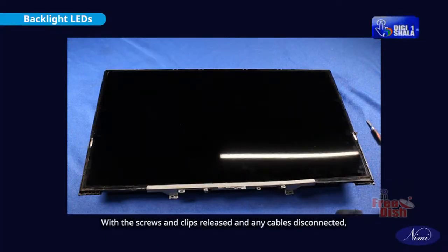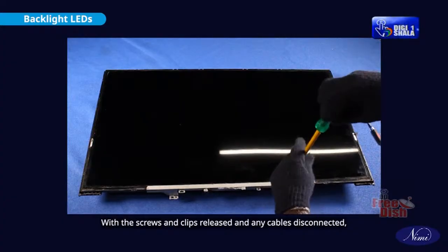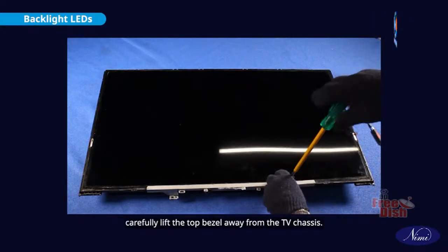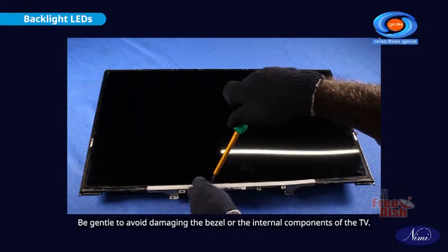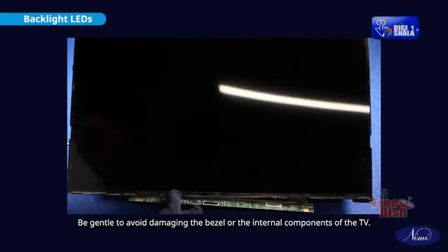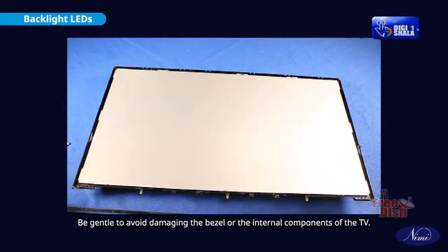With the screws and clips released and any cables disconnected, carefully lift the top bezel away from the TV chassis. Be gentle to avoid damaging the bezel or the internal components of the TV.